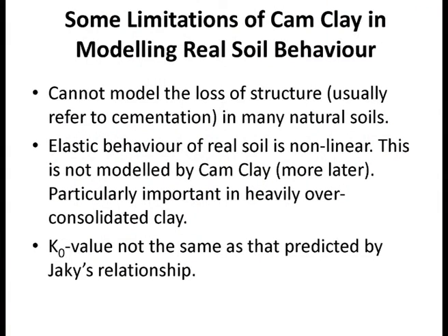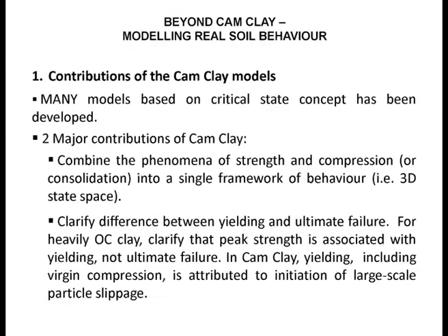So I will continue on forward. I will say something more about this, but these are some. And the K0 value is not exactly the same as that predicted by Jaky's relationship. I have already mentioned that, but I'm not sure if that is really a limitation, because although a lot of us believe that Jaky's is the reference, there's nothing to say that Jaky's is the correct value. Okay, so we also need to be careful about that.